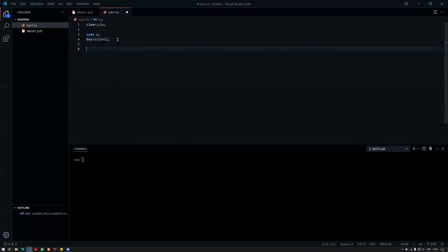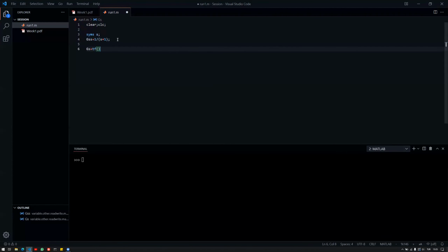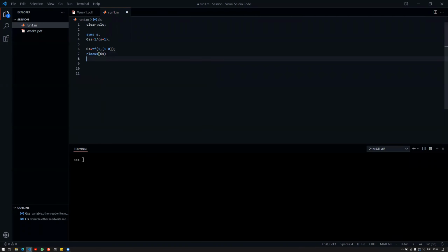But if I use, for example, a TF object, I will use just a single s in order to separate them. So if you see this, this is probably a symbolic variable. And if you see this, this is probably a transfer function object. Now you can define the transfer function using line 6. And you can call rlocus, and it will automatically generate the root locus plot that you're interested in. But first of all, what is the root locus plot?